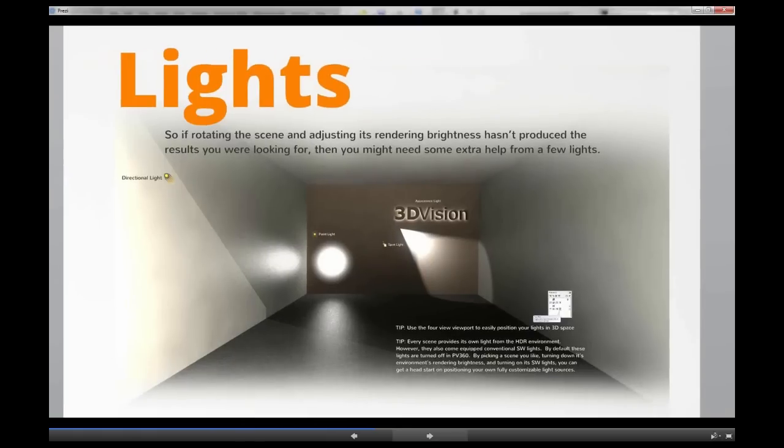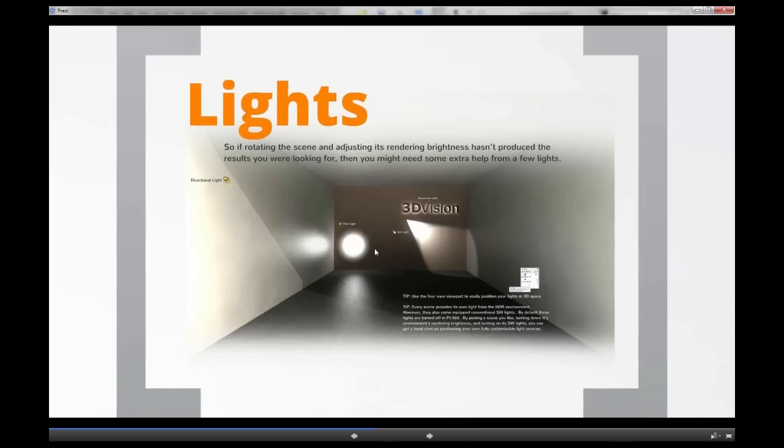All right, so I mentioned the lights. Again, you can look at this if you're getting into some of the advanced controls. But really, the only time you're going to want to play around with lights is if you're doing something a little bit more specific, like modeling a lamp on a desk. Well, then you could use a spotlight to actually have light emit from that object, or a little point light, like a glowing ball from inside a room or a closet or an enclosed space.